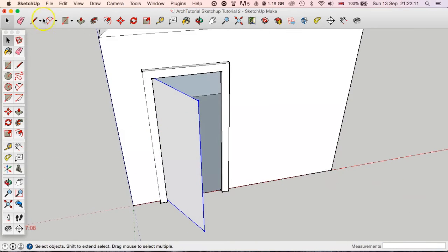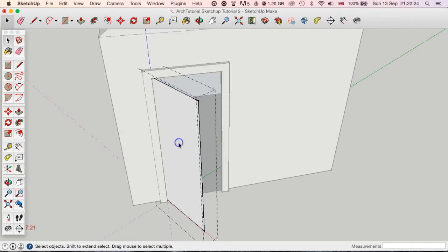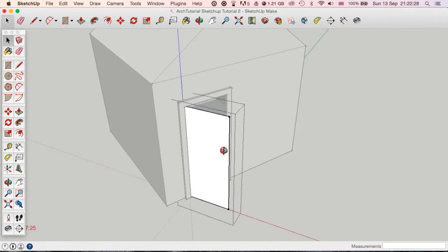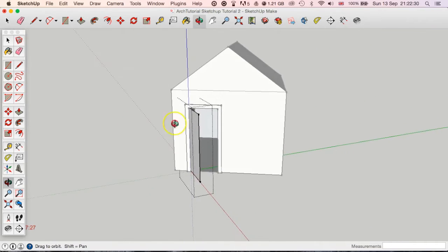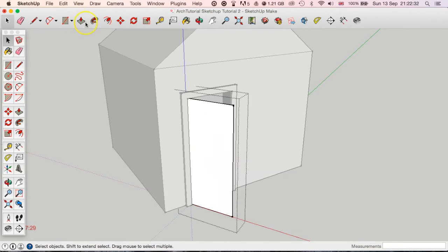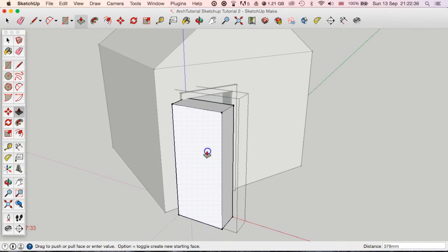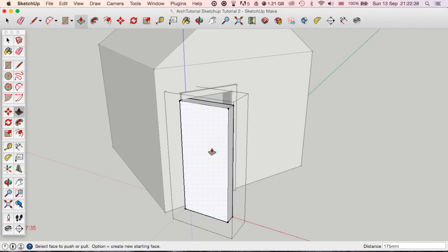But what you'll see now is that you can't use the extrusion tool on a group. And the way to get around this is when you click on the group, you then double click, okay, and you'll see that only everything within that group is now highlighted. Everything else not in that group has turned a darker grey. Now what you can do is edit that group individually using that 3D shape.